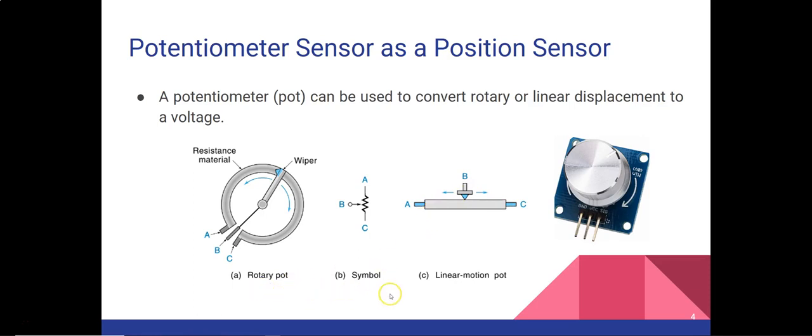The principle of a position sensor is the same as a standard volume controller, but there is a difference. A pot used for volume control may have an audio taper, which means the resistance changes in a non-linear fashion to match the human perception of sound. Whereas the potentiometer sensor is used to measure angular position, and it has a linear taper, which means the resistance varies linearly with the shaft rotation.